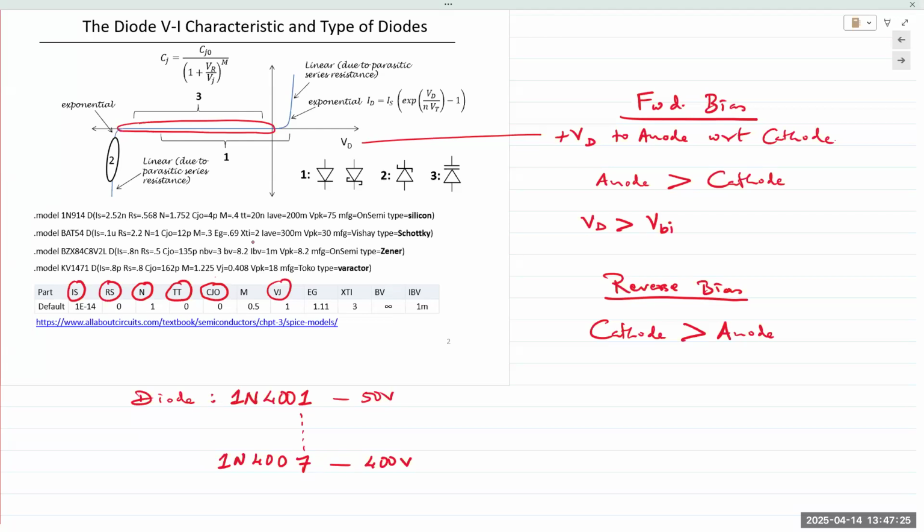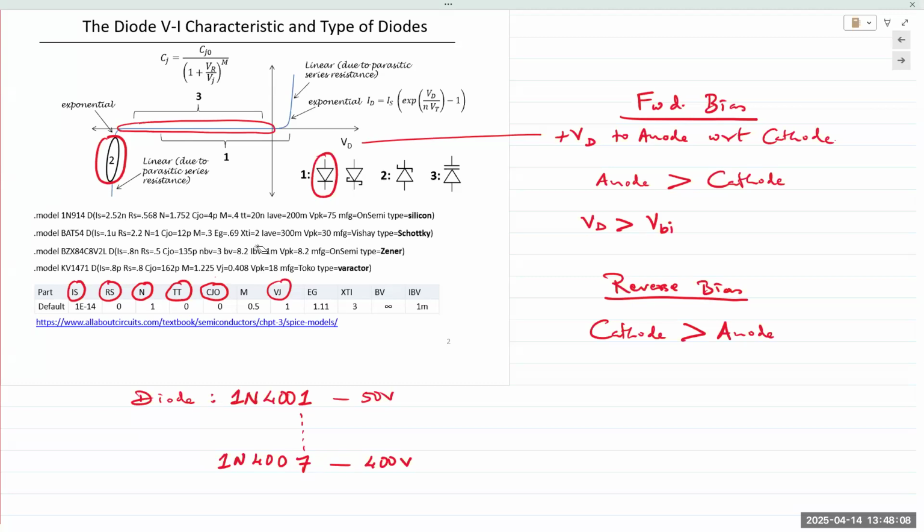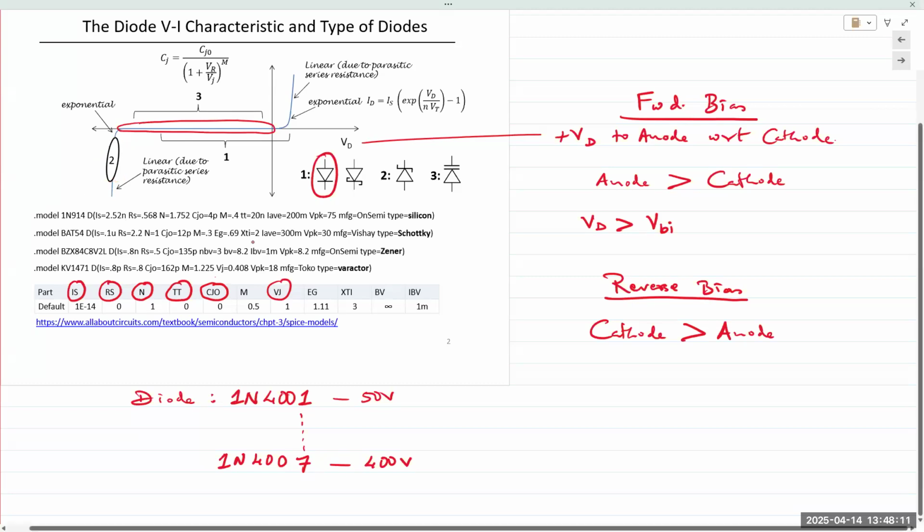Normal semiconductor diodes are represented by this symbol right there. If we operate a diode in reverse bias, at a certain point, exceeding the potential in the reverse bias for a diode, a phenomenon occurs. That phenomenon is known as junction breakdown, and the diode begins conducting heavily in the reverse direction. And that is noted by this number right there. So here we see some slope.